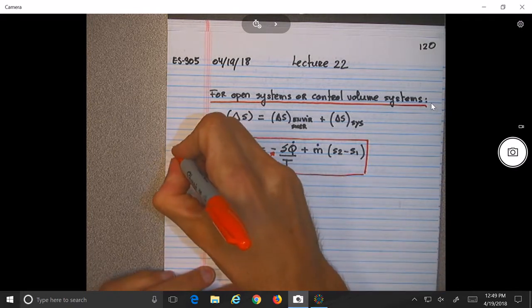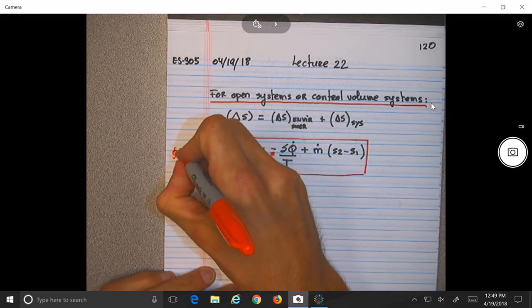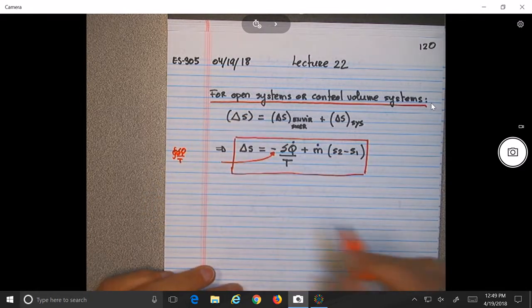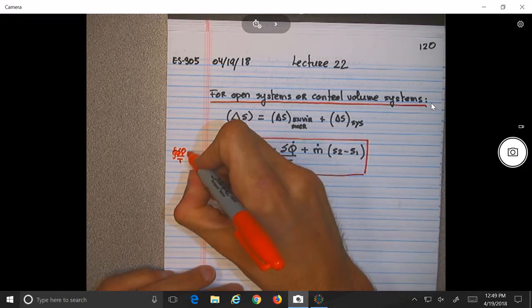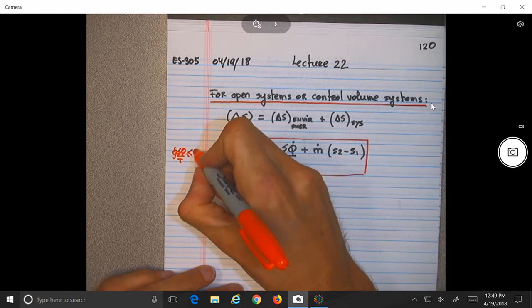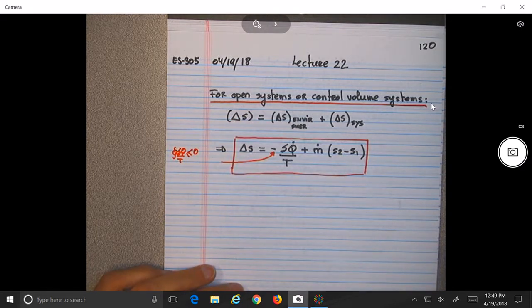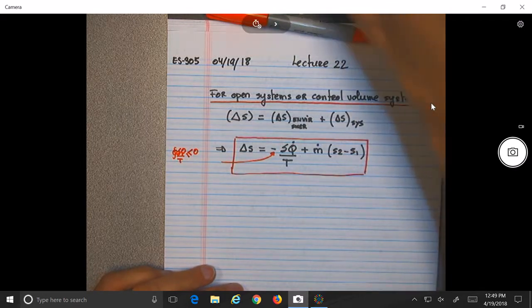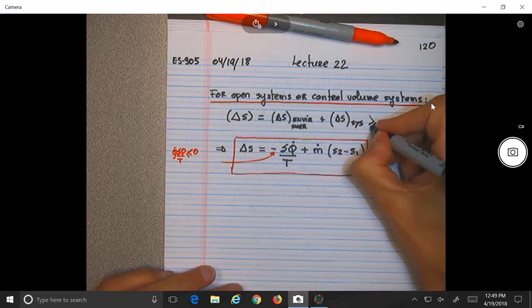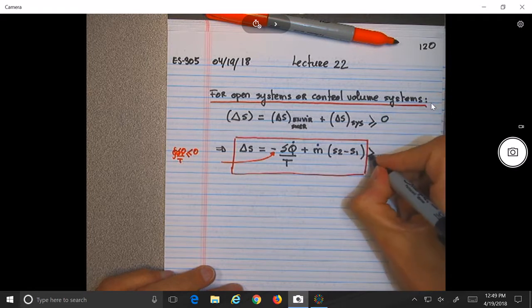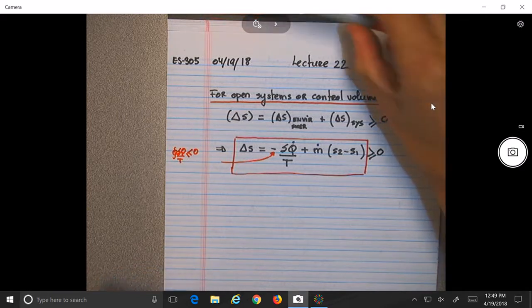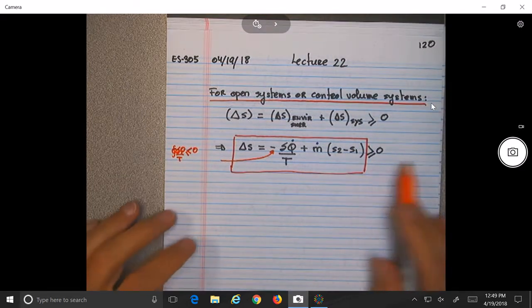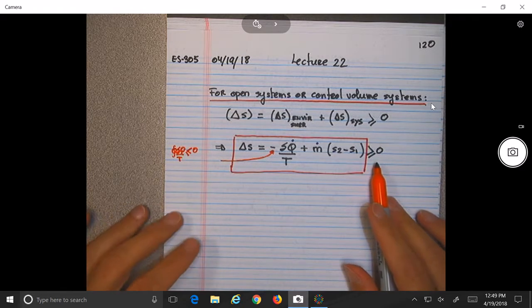It's because of the Clausius inequality. What was the Clausius inequality? If the integral of delta Q over T is equal to 0, it is reversible, and otherwise it is less than or equal to 0. Oops, I forgot the most important part here. This is the principle of increasing entropy, so it should be written like this. No mistake, but I forgot to put it.